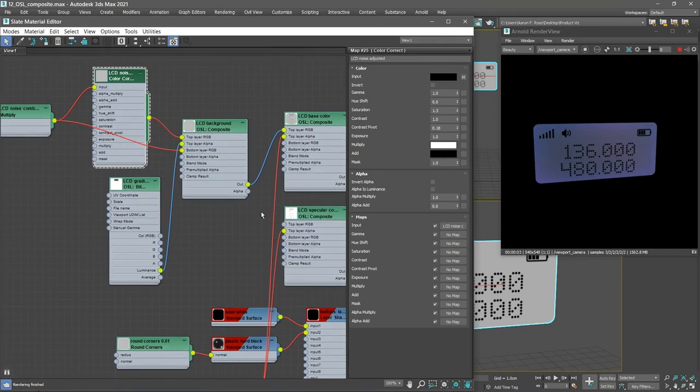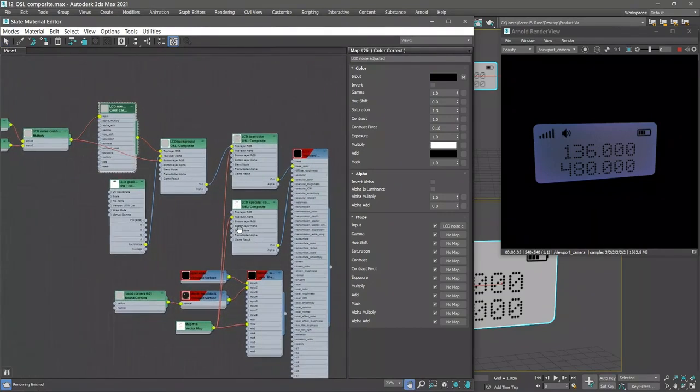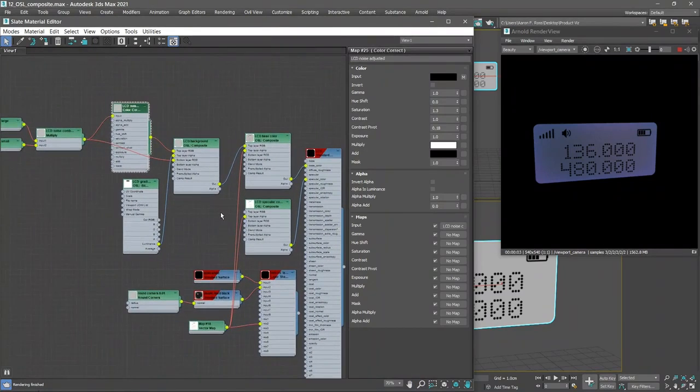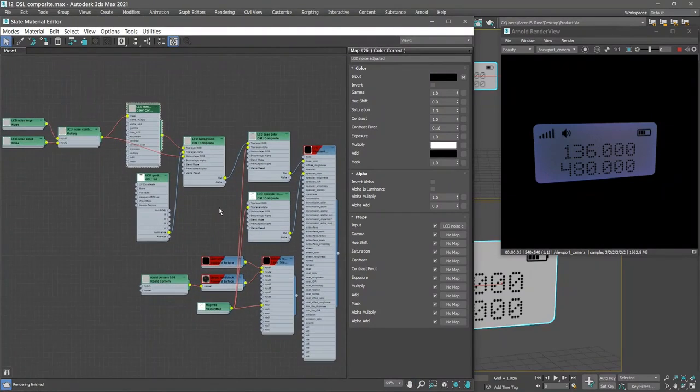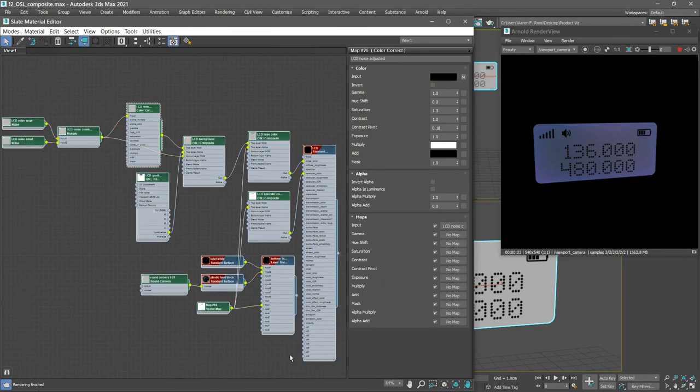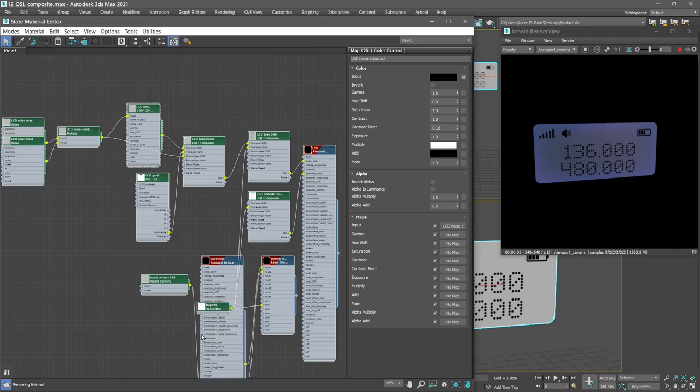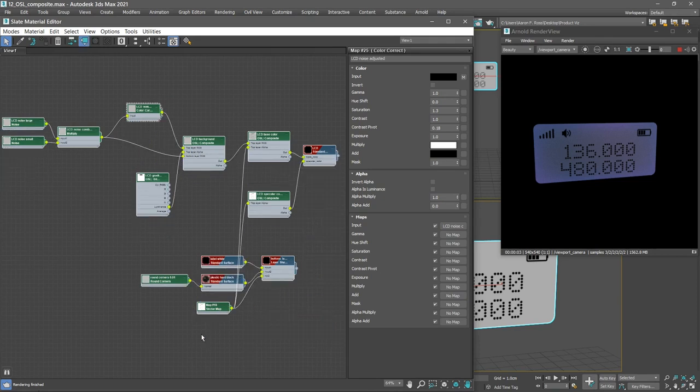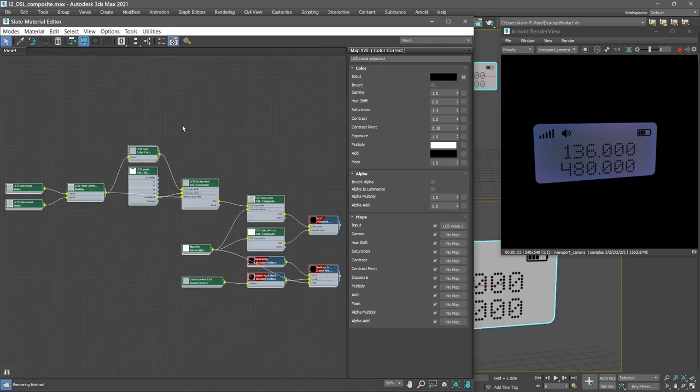All right, that is our shading network. It looks a little bit daunting, but it's not quite that complicated actually. We can make this a little bit easier to see. We can select all of the nodes and hide the unused node slots. There's a keyboard shortcut for that, which is H. Might need to press that a couple of times. And then we can reorganize the graph. Click up here on the graph to lay out all. And here's our shading network.